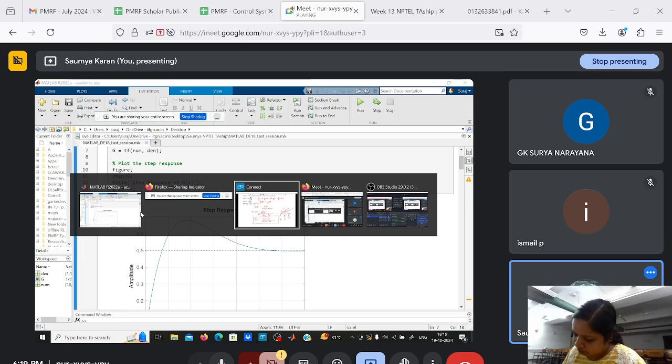You'll get the answer. Then we look for breakaway points to know if there are roots that are coming in and they would break in to go to some other part, or if there are two branches coming from two poles and they would break in to go to zeros, or break away to go to poles. So any of these things can happen.